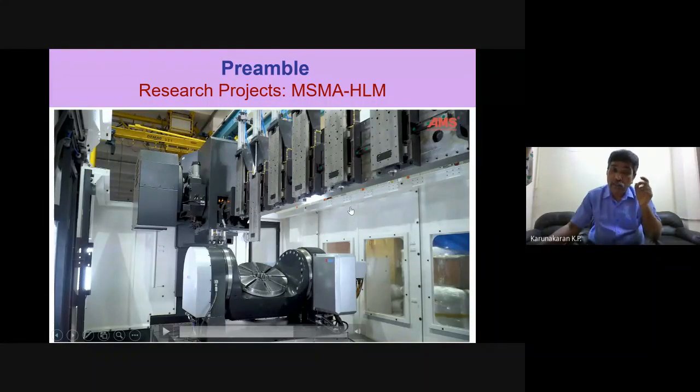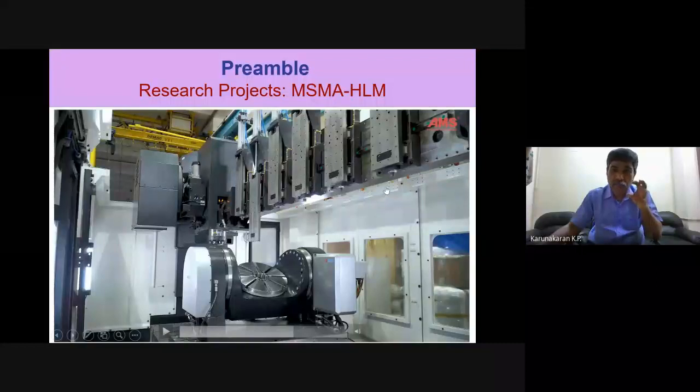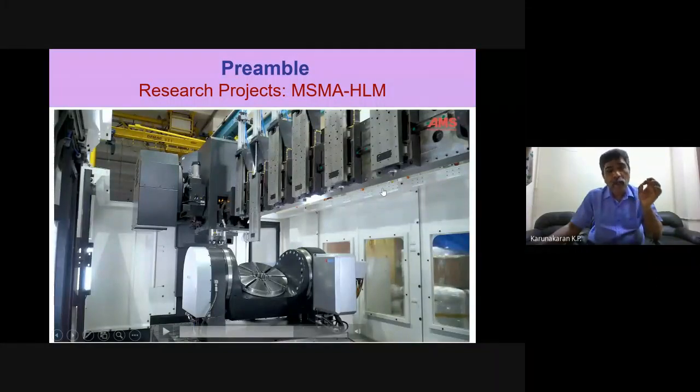So what we do is, on the same machine, we try to reduce the residual stress by preheating using an induction heater, which will be on the right hand. And after the residual stress is minimized, after the layer is clad, we go for hammering. You know, we have a pneumatic hammer, a very cheap 2,000 rupees hammer. It works very effectively.